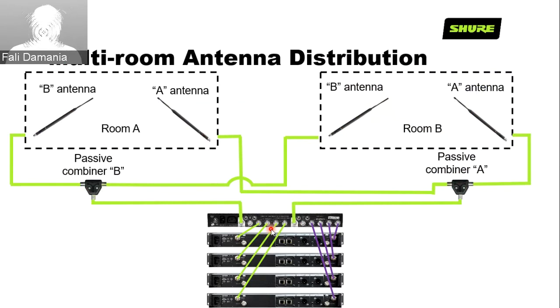A small consideration I'll give you for placing the antennas in these rooms, especially if the rooms are not divided by, say, a concrete structure. For example, in a large ballroom, you have air walls, and you need those antennas to work independently and simultaneously. It's very important to now select the correct types of amplifiers. In fact, in this kind of situation, if I ask you what the medium barrier between these two rooms will be, your answer should be that it should be at least a concrete wall, so that these antennas from here don't interact with these antennas from here. If we were using these omnidirectional UA8 antennas, and this was actually an air wall or a wooden partition, or those partitions that you have in ballrooms, then you would practically turn these into directional antennas so that they only interact with what's happening in this room, and to an extent are blocked from all the interaction that's happening here.